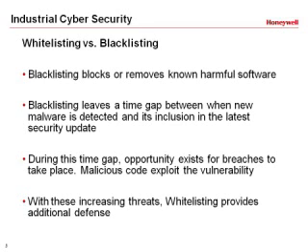With the increasing threats to industrial cybersecurity, whitelisting provides an additional defense. Application whitelisting permits only applications and executable files which are on the approved list and blocks everything else. The administrator of the whitelisting system must determine what is safe and be vigilant to keep the list current. And he or she must make sure critical applications are not omitted from the approved list.